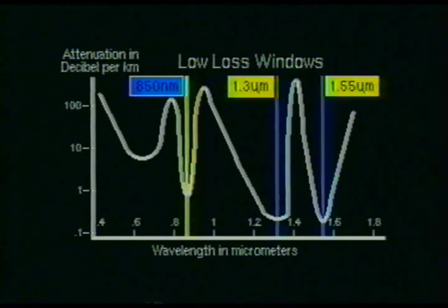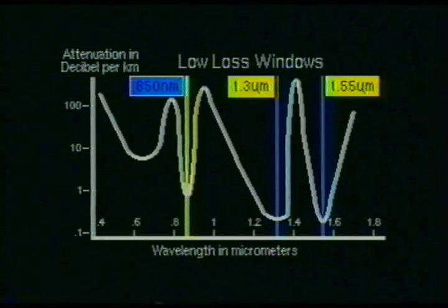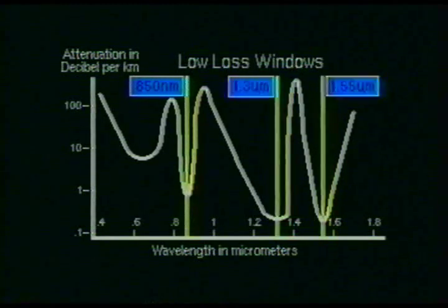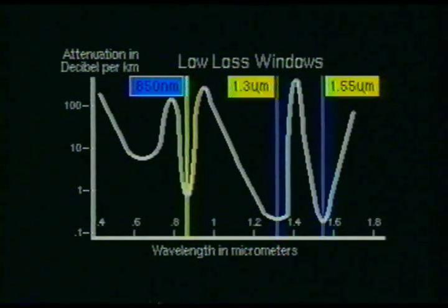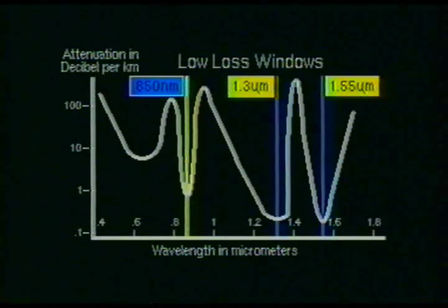The longer wavelengths of 1.3 and 1.55 micrometers exhibited a typical attenuation of approximately 0.2 decibels per 1,000 meters. The only drawback was the expense of producing the cable. While research was being performed on the fiber cables, laser research and development was also being carried forward.